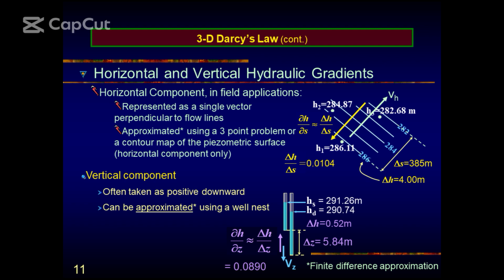The phreatic surface is the surface, when you dig, let's say, a piezometer, a test well, the level of water in the well. But then, the water table could be somewhere like this. Of course, more often than not, if you have abstraction, you have cone of depression.